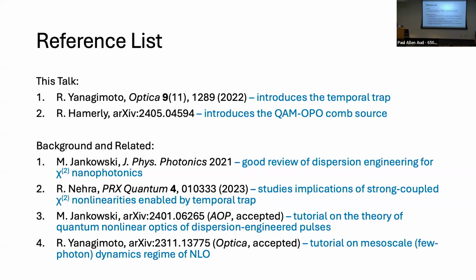So the coupling is designed differently between all pulses? Well, if you think about it, if it's a directional coupler, it's also important to note here that you only ever couple into and out of the cavity at the fundamental frequency, not at the second harmonic. The second harmonic only exists inside of the cavity to give you that nonlinear interaction.